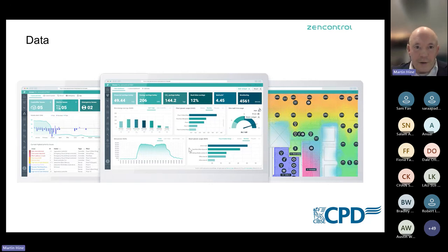In addition to monitoring, there is the facility within the lighting control to make changes to the system, changing time regimes, fade rates, light levels. All of these things can be adjusted from the head end.